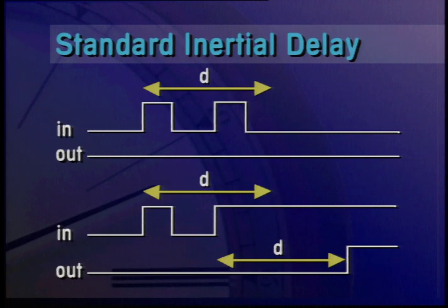Both of them use inertial delay, but Verilog has a second inertial delay model. Verilog's original delay model is just like the VHDL version. If an input pulse changes before the gate delay, then the output event would be unscheduled from the future event list and then rescheduled for the new time.